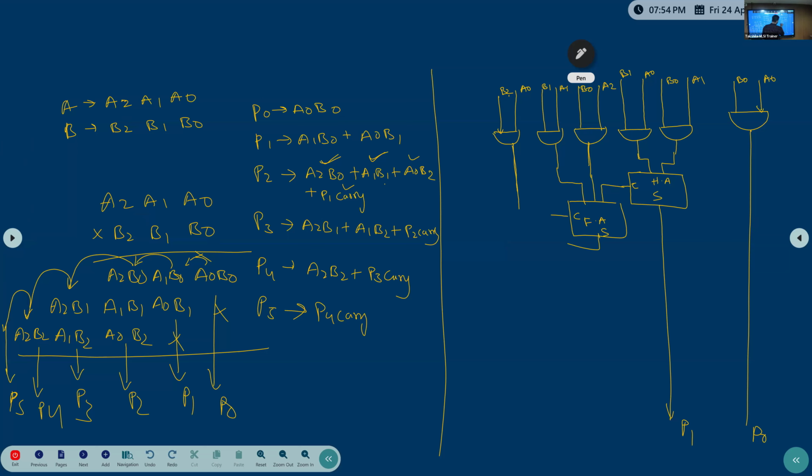So whatever sum comes, this carry and all together, we need to give to one more full adder. Whatever comes now is P2, and whatever carry there is, is for the rest. Understand, right? Here there are 4 bits I need to add, that's why 2 full adders are used. Sum and carry both go to the same adder. The final result will be P2, and this one will be the carry.